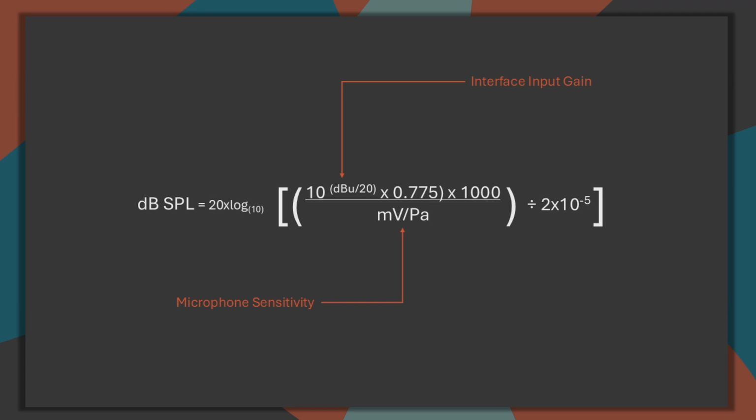Please note that this is not the correct method of calibrating your system, but I give you this tool so that you can start playing around with SPL measurements. To do this properly, you need a calibrator.